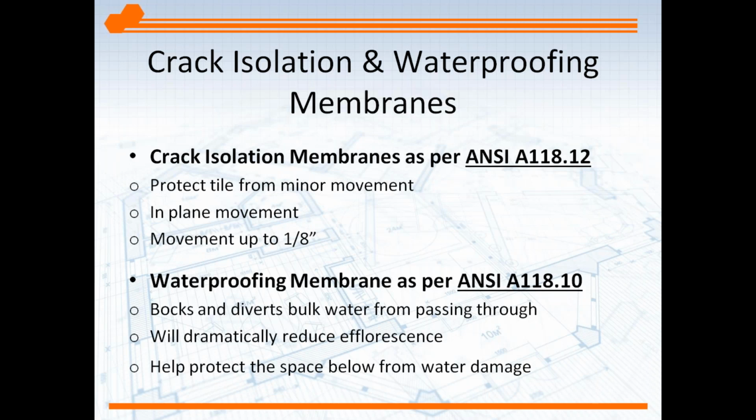We see a lot of commercial installations where they use the waterproof membrane throughout the bathroom area, not just in the showers, for that exact reason, or maybe in high-rise or multi-residential. There's tremendous savings in keeping that water inside of that bathroom as far as damage to the spaces below.